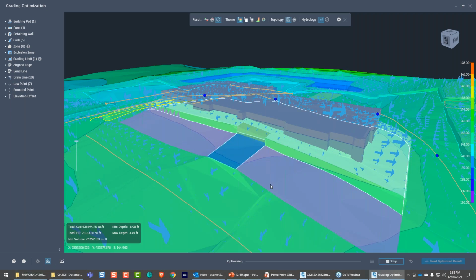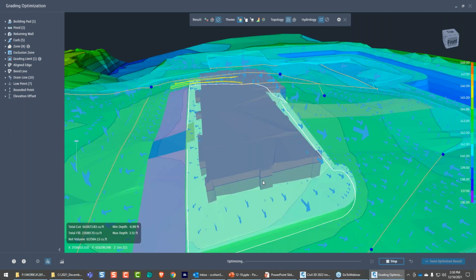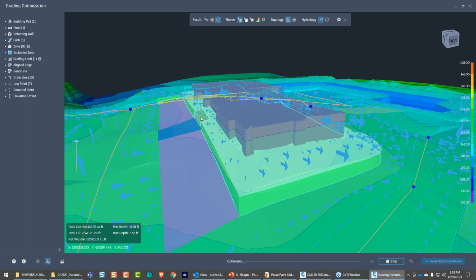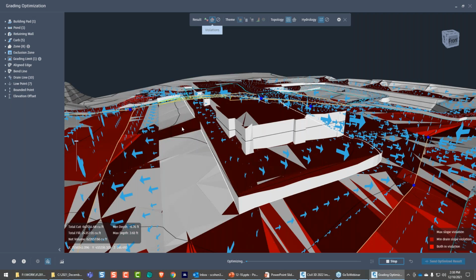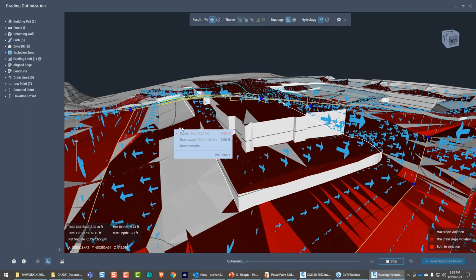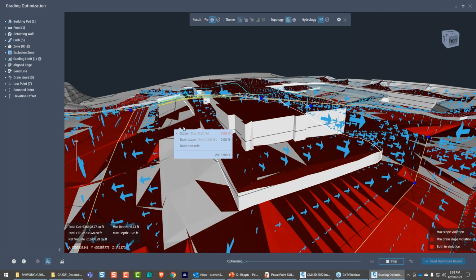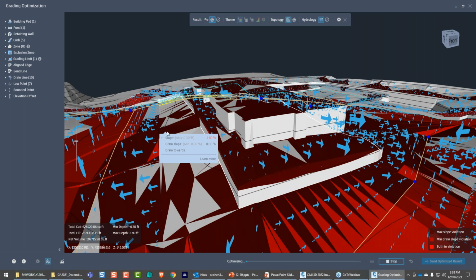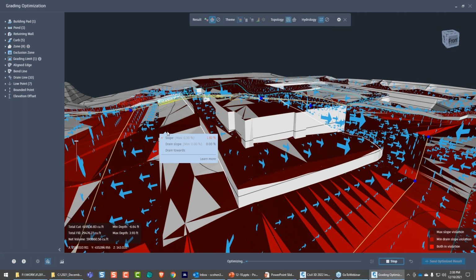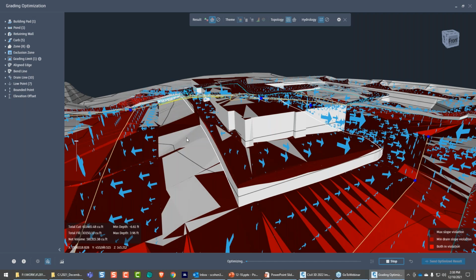You can see it locking in that slope, and also locking in this one as well. If you want to see what slope it is, take it to the violations and then hover over it. It will show you it's at 3%. Oh, that actually should not be that way. That should be less than that. There we go, it must be some leg it's stuck on. So 1.82 and then 0 is what it's getting, so yeah, it's violating the 0.3. Like I said, I can change it afterwards if I don't get what I want.